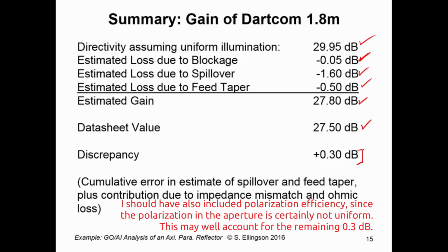Now you might ask, what's the remaining error, this 0.3 dB? And this is hard to say. We'd have to do more detailed analysis and maybe even some measurements to support that analysis. But it's certainly the cumulative error in the estimate of the spillover, the estimate of the feed taper, plus there will certainly be some impedance mismatch and some ohmic loss. Can't make that zero, but that's, again, probably very small.